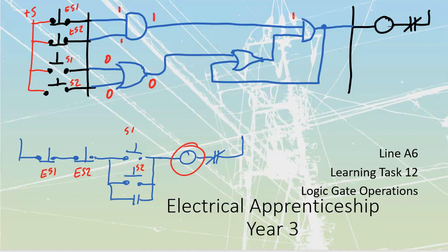Now we're going to start with our system off. To be honest, I'm not going to go through the very first time we apply power to the system because it goes through a little bit of setup and contact race. We're going to say that right now the system is off. If this is off, that means there's a 0 being fed through into here, and that there's another 0 feeding from there into there, which means that this output would also have to be 0. And what we see then is that a 0 on an AND gate makes our output 0, and so it holds this. We basically formed what is referred to as a flip-flop or a latch or a memory state, all sorts of different terms that we can utilize for it.